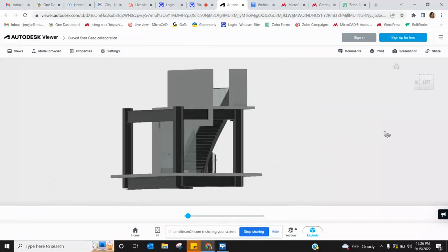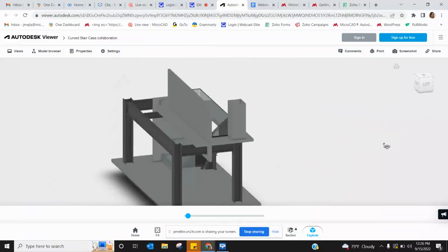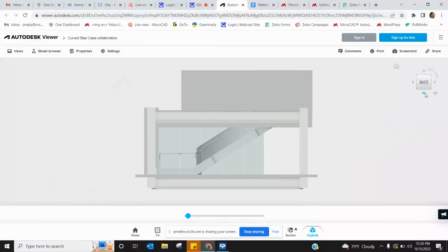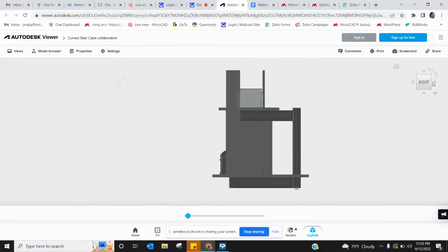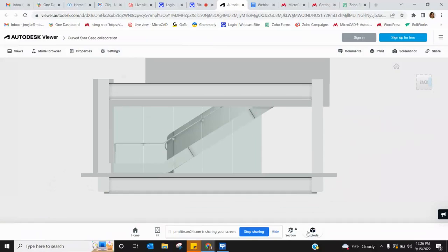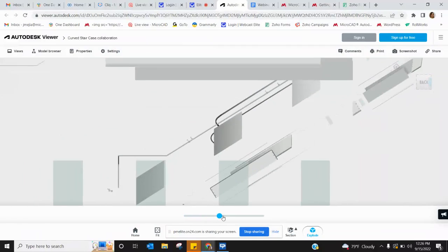So if it's a really large BIM model, I only need a certain area for the staircase. I can define that as my view that I want to reference. It even remains associative. So if the Revit user updates the revised data exchange, the Inventor model reflects that as well. So this, of course, eliminates any need to email Revit files, revisions that need to be imported into Inventor.